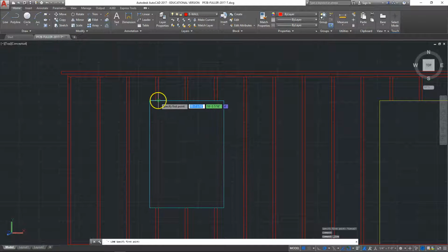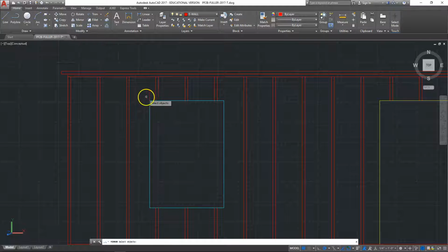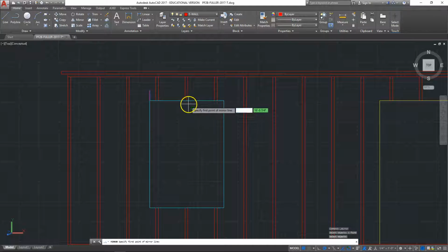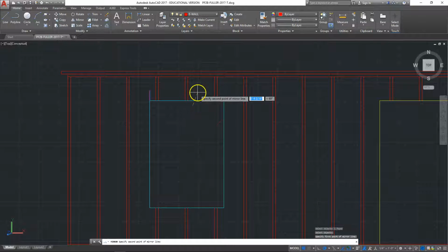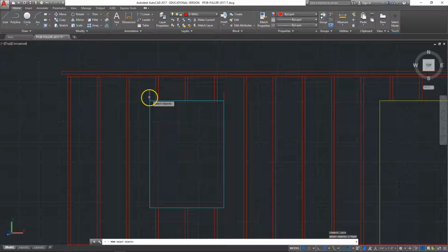To make the header, place a vertical line 5.5 inches from the top corner of a window upwards. Mirror this line to the other side of the window. You may have to turn off some snap behaviors to find the center mirror line. Either offset or move the lines 1.5 inches outward and connect them horizontally to each other.